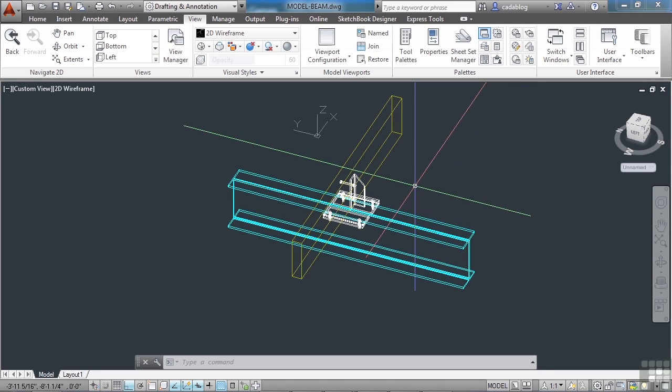Now, if you're using a Logitech mouse like I am, sometimes it doesn't work. In order to get a Logitech mouse to work, it seems that you have to download their special driver software. Do that and then turn on the settings for the scroll wheel commands inside AutoCAD. Otherwise, most mice will work just fine, but I've found that to be true. So a bit of a heads up if you have a Logitech mouse and it's not working for you.